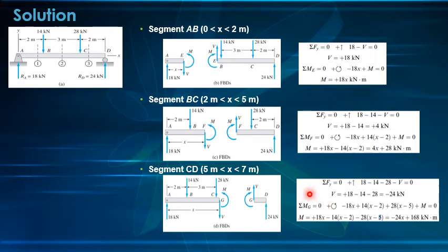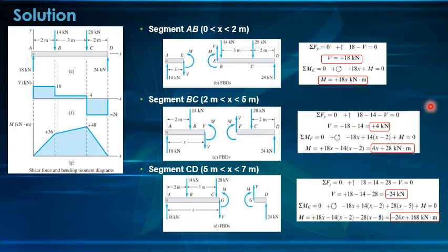So these are the expressions derived for the shear force and bending moment for each segment of the beam. For part 2, as mentioned earlier in the problem, we need to draw the shear force and bending moment diagram. In our procedure, it was stated that it is most desirable to draw the shear and moment diagram below the loading diagram. So, this is what you should do every time you solve a shear and moment diagram, class.